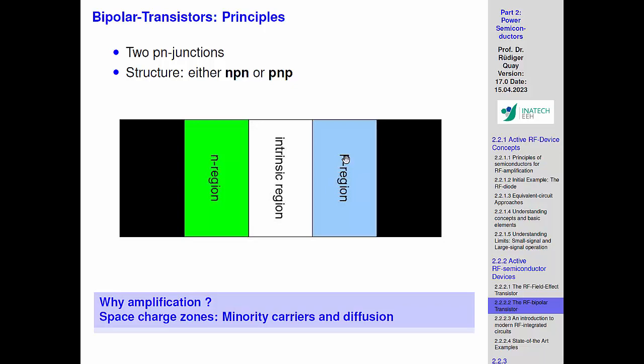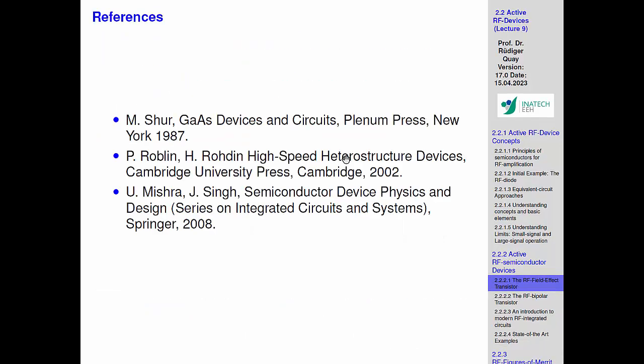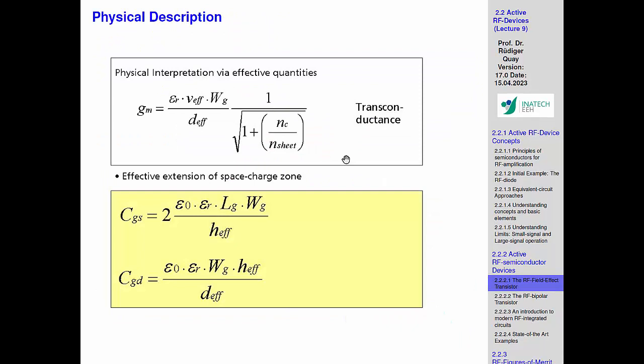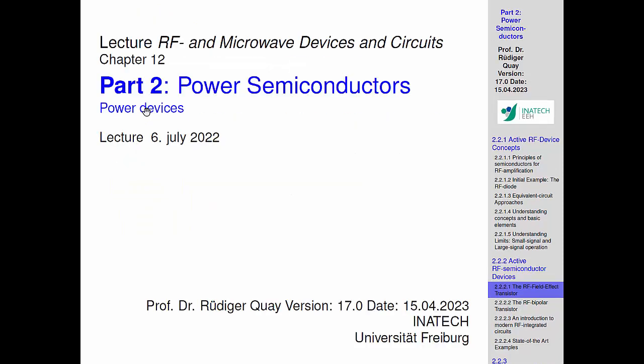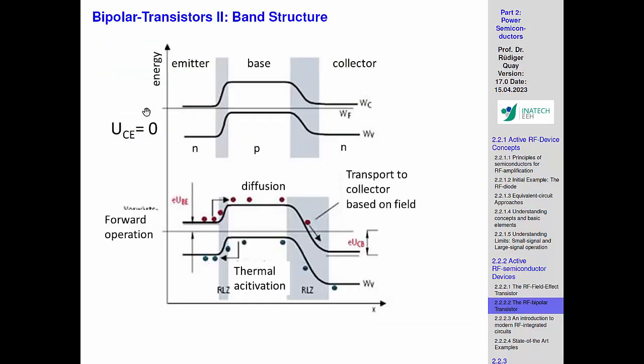And that's interesting because if you think about what we did here, we always wanted to have a high gm. So we want a strong current change. And why on earth should this work? So first, on the top, we take these two diodes and you're essentially building two barriers. So in no way is a current flow possible, because these are two inverted diodes.